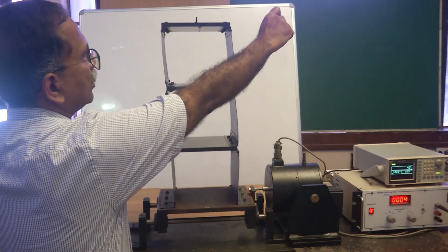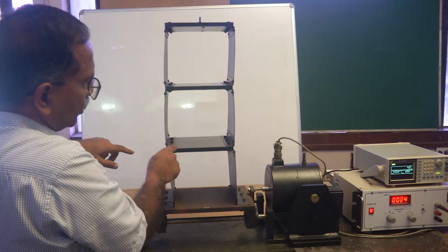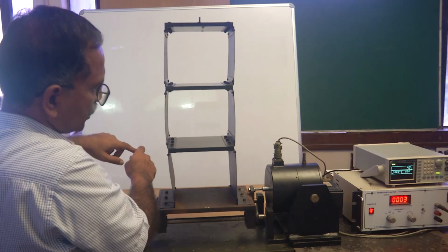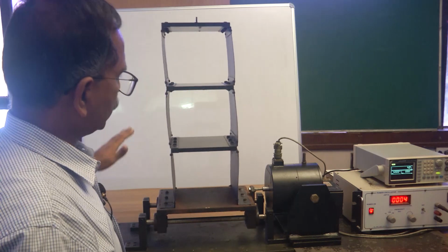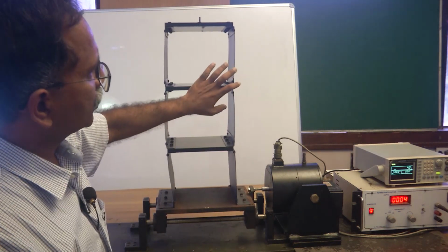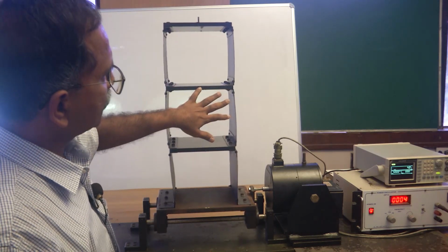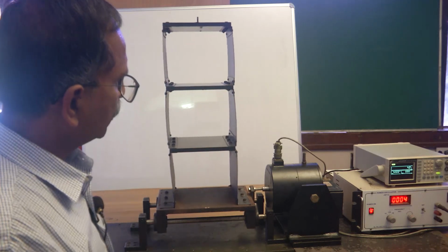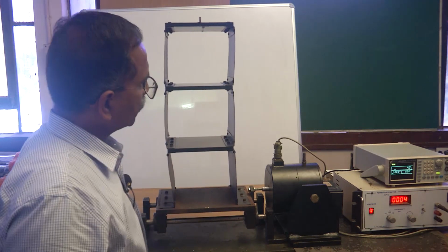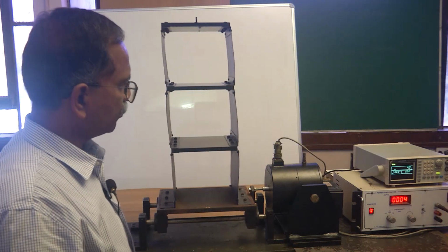This is 1 unit amplitude, and then you can see that there will be maximum amplitude on the left side, and then going back to 0 here. So this is how the mode shape would look like. There will be a node position here, somewhere nearby this plate, and that is the reason this plate has much lower amplitude as compared to this one and this one. That's how you can figure out or verify the mode shapes corresponding to individual natural frequencies.